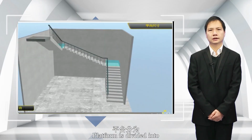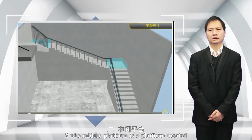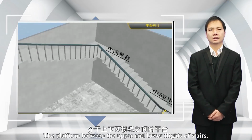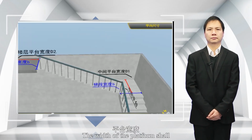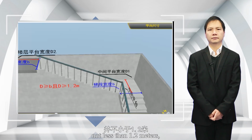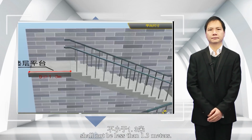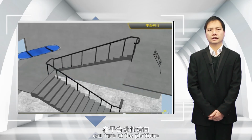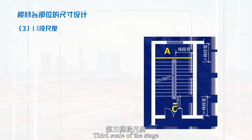Platform is divided into: 1. Floor platform, a platform with consistent floor elevation. 2. The middle platform, a platform located between the upper and lower flights of stairs, for parallel and zigzag shapes, or multi-flight stairs. The width of the platform shall not be less than the width of the staircase, not less than 1.2 meters, and the width of the scissor staircase platform shall not be less than 1.3 meters. Permanent buildings should also ensure that the scaffolding can turn at the platform, and the platform width should not be less than 2 meters.